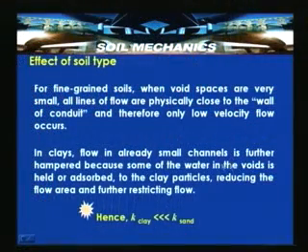In clays, flow in already small channels is further hampered because some of the water in the voids is held or adsorbed to the clay particles, reducing the flow area and further restricting the flow. So in clays or fine grained soils, the physico-chemical environment surrounding the particle influences the flow conditions. In sandy soils, the loss of frictional drag at the edges is not absent, except that the velocity is maintained and high flow is maintained. So, the seepage velocity is higher for a coarse grained soil than for a fine grained soil.